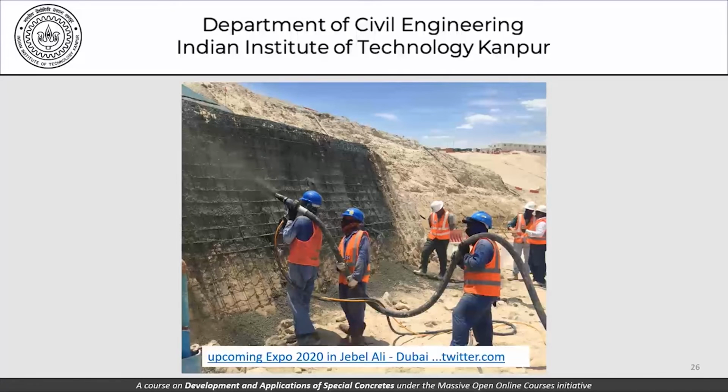We can see this reinforcement which has been placed, and we are trying to place this concrete here against the slope. No form works, and we are expecting that as far as the shotcrete is concerned, this is the reinforcement that we have placed, and let us say it is placed somewhere here, and this is my surface. So if we are gunning it here, the concrete is expected to reach all these places at the back and have a deposit which will become something like this with reinforcement bars somewhere here.